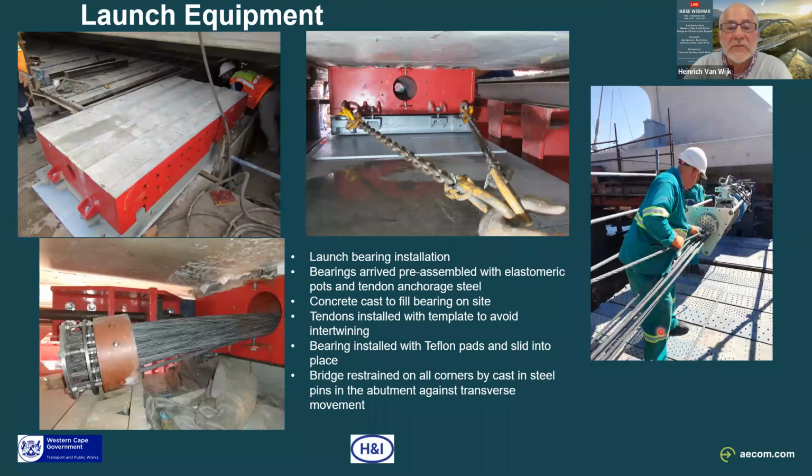These are just some visuals of your launch bearing, which arrived on site pre-assembled. The steel box was filled with high quality concrete, and the sliding pads were special Teflon pads, dimpled Teflon pads. And during this whole process, we had to restrain the structure with specially designed pins to be sure that it's stable during all stages.